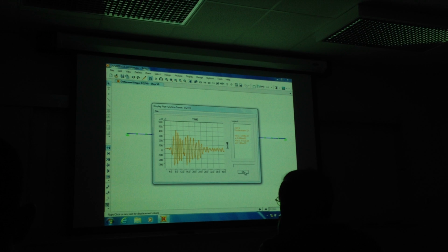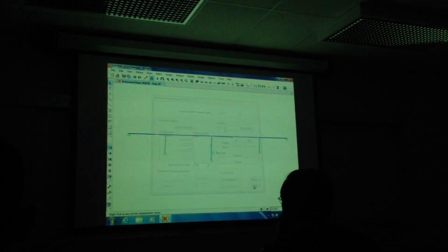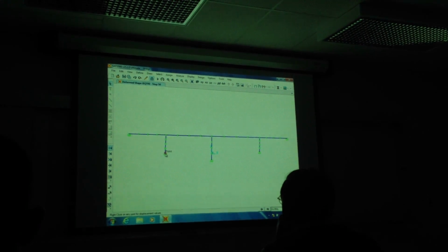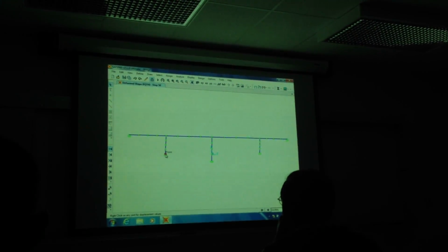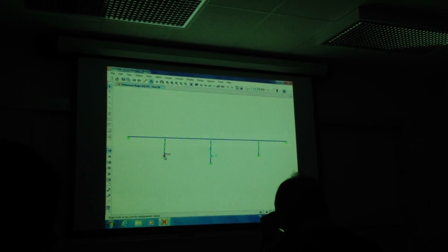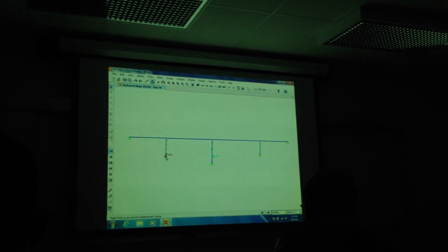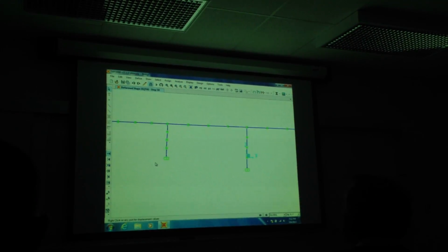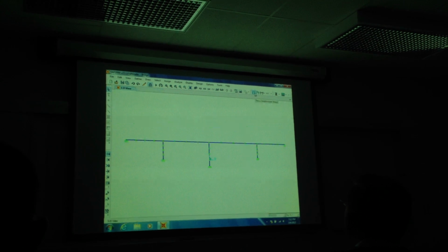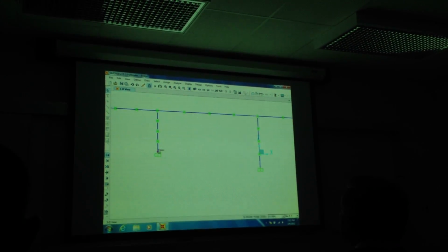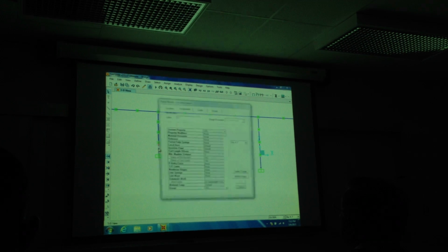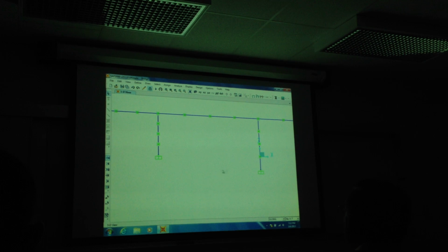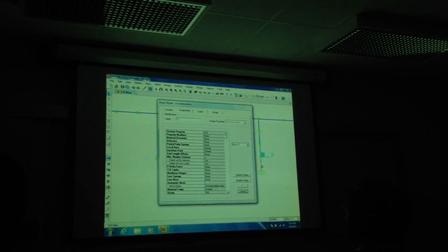Let's say we want to know what the moment is at the bottom of the column here. So what did we say we're going to design the column for? What moment capacity will it actually have? About 5,000 kip feet, right? Something like that. Well, let's see. Let's click on here. And as an example, pick this member, right click on it, it's member 26, okay? And then we'll look at this one too. This one, I'm right clicking on, it's member 30.